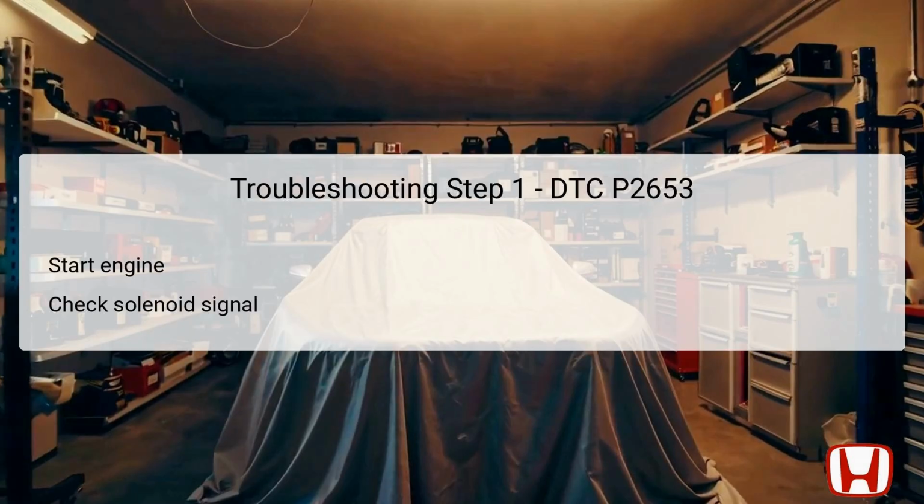The first step in troubleshooting DTC P2653 requires starting the engine and monitoring the rocker arm oil control solenoid's functionality. The aim is to confirm whether the PCM is correctly receiving and interpreting the signal sent from the solenoid. When the engine is running, a proper signal should be visible on the diagnostic scan tool. If the signal is absent or inconsistent despite the engine running, this suggests that the solenoid or its wiring may be faulty.